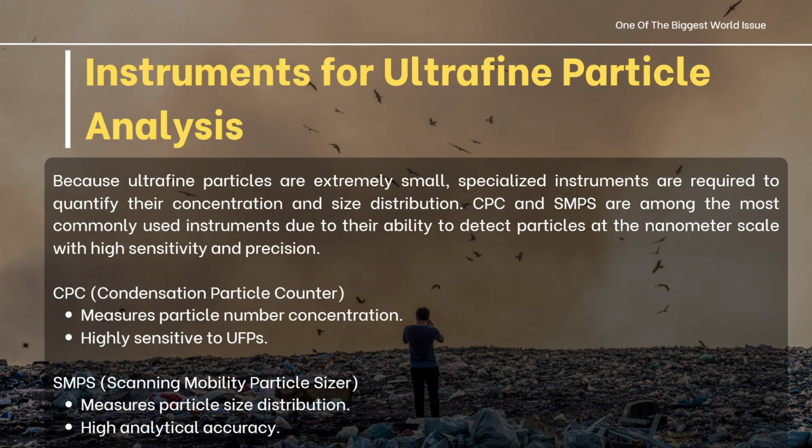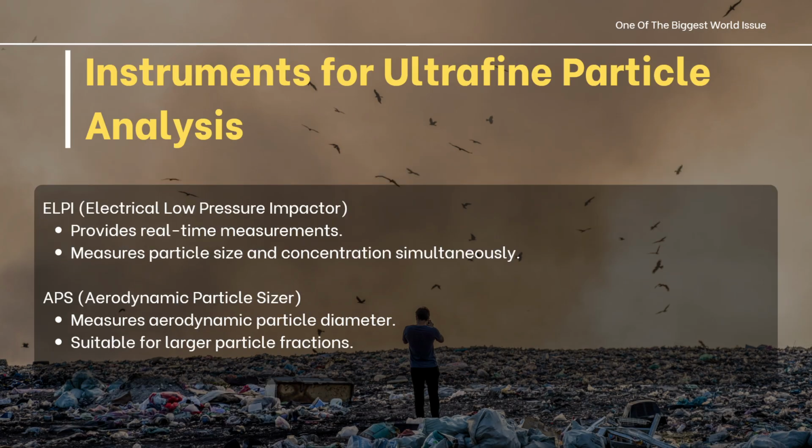CPC is the condensation particle counter, which measures the particle number concentration and is highly sensitive to ultrafine particles. SMPS, the scanning mobility particle sizer, measures the particle size distribution with high analytical accuracy. Now for the ELPI, or electrical low pressure impactor, it provides real-time measurement and measures the particle size and concentration simultaneously. For the APS, or aerodynamic particle sizer, it measures the aerodynamic particle diameter and is suitable for the large particle